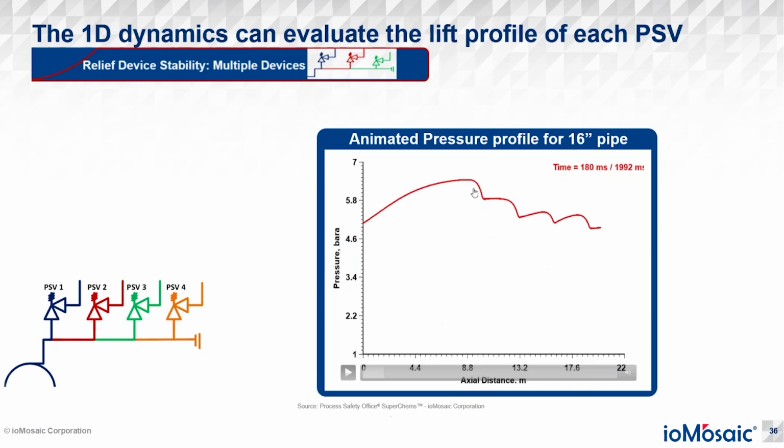It's quite a nice thing to see, because if I've got four PSVs in a row and I want to look at mass flow and pressure, this is kind of my idyllic profile. You can see PSV1 opens, PSV2, PSV3, PSV4, so they all follow the bumps. Very nice. But unfortunately, we do have chattering in all four of the valves, and we have that coupling motion.